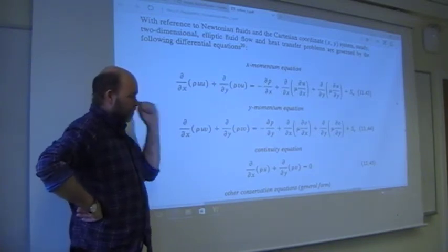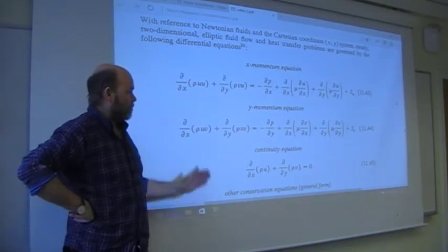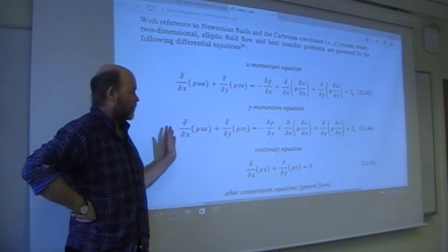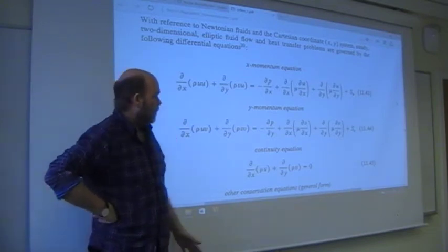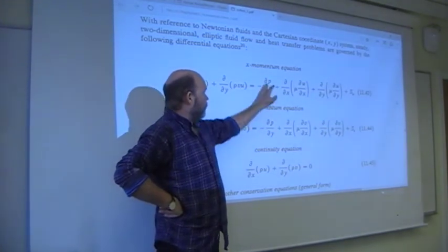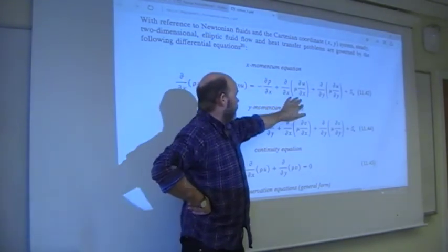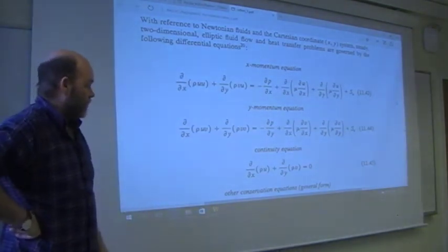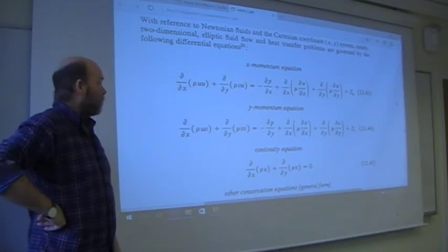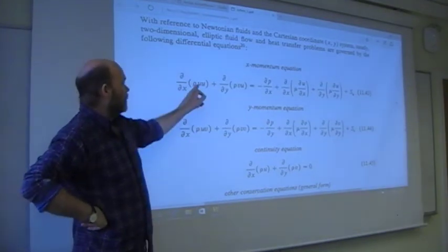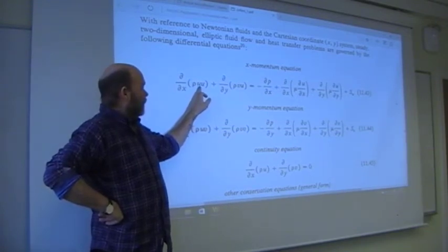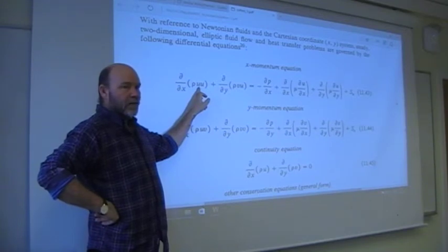If you can recall, we chose staggered mesh systems when we talked about finite differences in a structured mesh. The reason is we only have a single derivative of the pressure and a double derivative of the velocity. So if you discretize straightforwardly, for the unknown velocity u, when you're focusing on him, the pressure where you are standing does not enter the algebraic equation system.